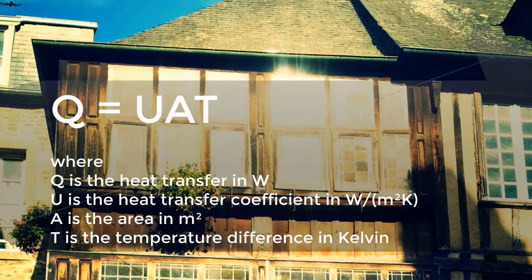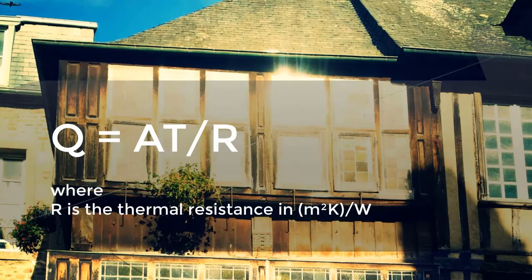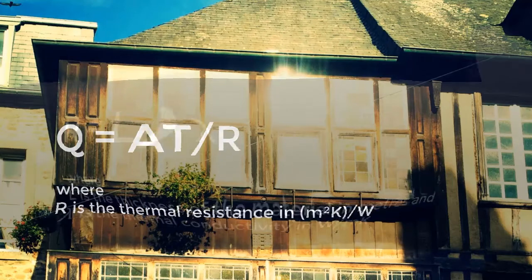Heat transfer is given by Q equal to UAT, where Q is the heat transfer in watt, U is the heat transfer coefficient in watt per meter squared Kelvin, A is the area in meter squared, T is the temperature difference in Kelvin. And we know that U is inverse to R, where R is the thermal resistance in meter squared Kelvin per watt. Therefore, Q equal to area times temperature difference divided by R value,